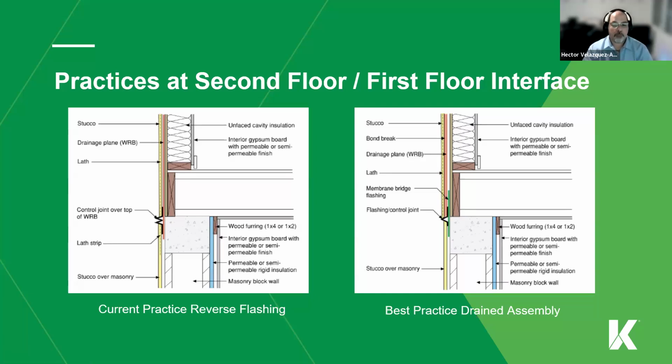Be careful with your maintenance people. They typically say, hey, I got a leak, and they come in and seal all this area out. And you will find a big blob of sealant across my building. Then you seal the whole water inside of your system. You had a different area that was having issues, and the place where the water was coming out, you just blocked it. So those things you have to be very careful about.